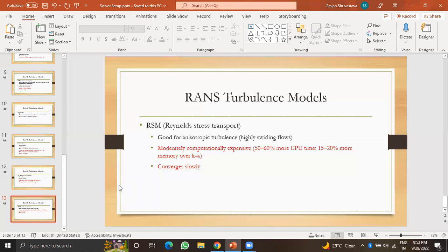Basically, you can figure out the pressure-based and density-based solver, but for turbulence models, yes, you need some previous experience. And like I said, if you are confused about it, just close your eyes and click on K-omega SST, and that's the model that we'll be using in most of our upcoming simulations.